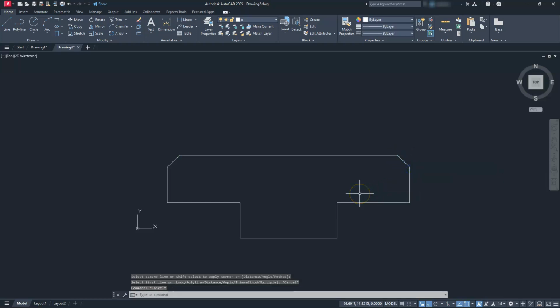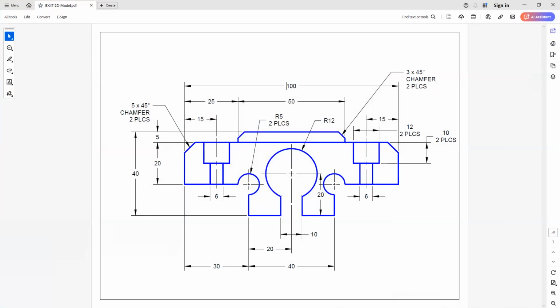Okay, from this point, let's take a look at it from AutoCAD, from the drawing, and then we can discuss it more, because we're going to have another chamfer up here. And once I explain this concept, it should be real easy for you. So what are we looking at here is that it has a distance in front of it, and these numbers sometimes can be interchanged, but you should still be able to recognize one of them is going to have an angle on it, which is our 45 degrees, and the other one is the distance.